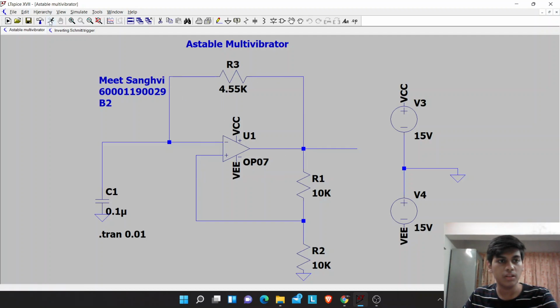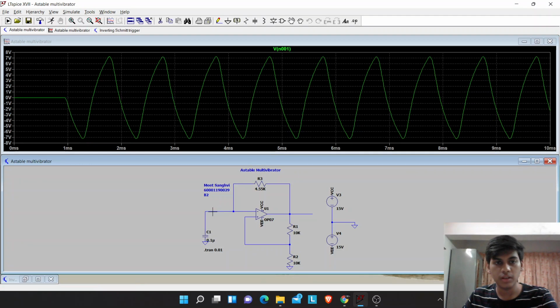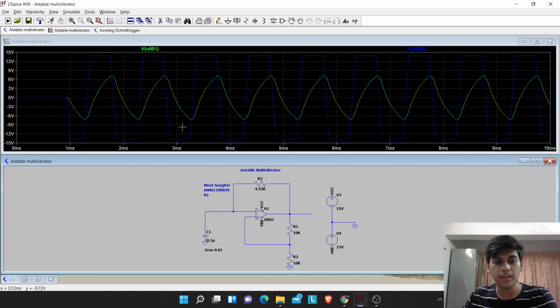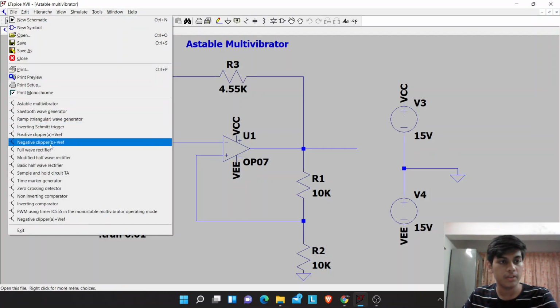Now we will run the circuit. This is the Vin. Click over here. As we can see, the input is like charging and discharging of a capacitor, and the output is the same as the Schmitt trigger, a square wave. So this means that the circuit is capable enough to amplify its own noise and give us an output. Yes, now we will move towards the triangular wave generator.